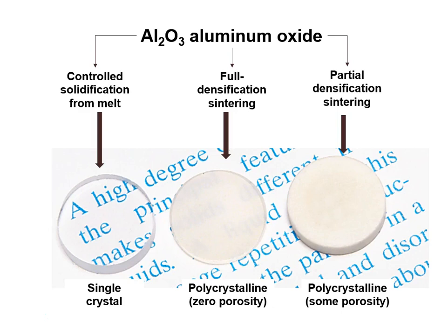So it is a multi-phase structure. So light that impinges on it will bounce off of all of those aluminum oxide air interfaces, scatter, and not penetrate. So you get a very opaque material. It also has very, very poor fracture toughness, even for a ceramic, since all of those pores act as little crack starters, which we'll discuss later as well.